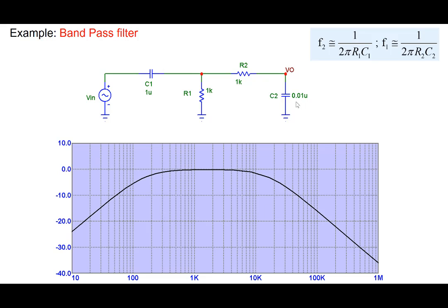And you can check it out by sketching your own Bode plot, that particular filter would have provided you with more attenuation in the band in which you don't want frequencies to pass. So it would have been a better filter, a filter which attenuates the unwanted frequencies, in that respect here.